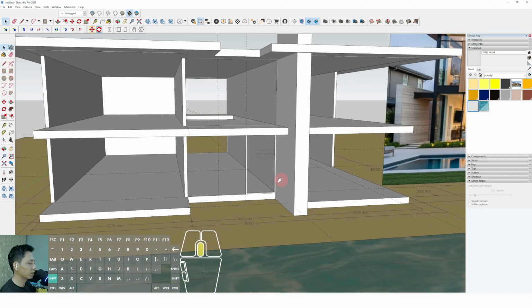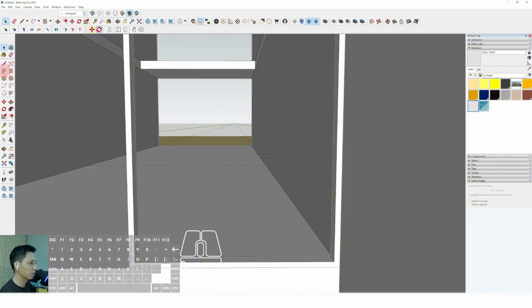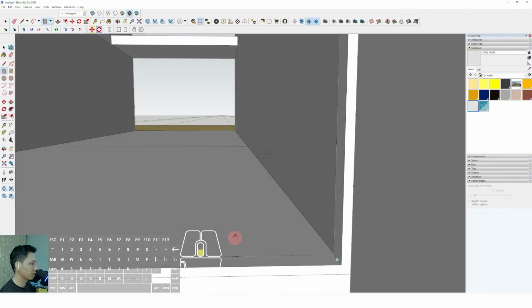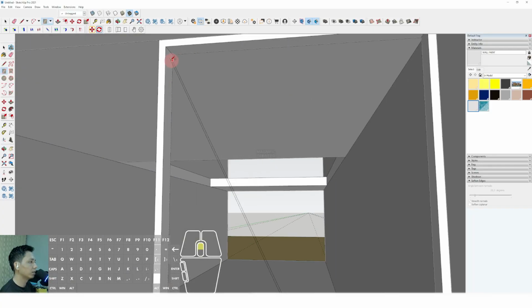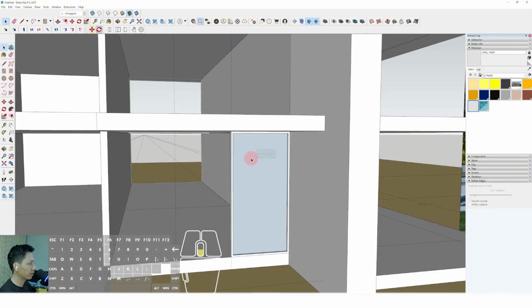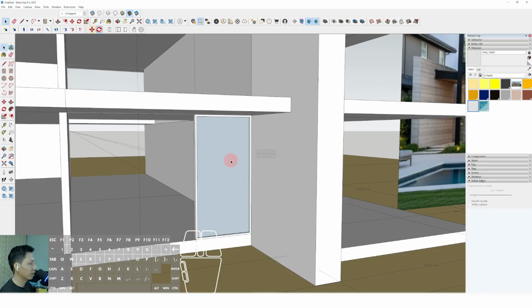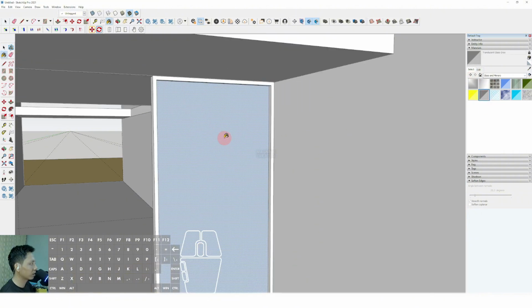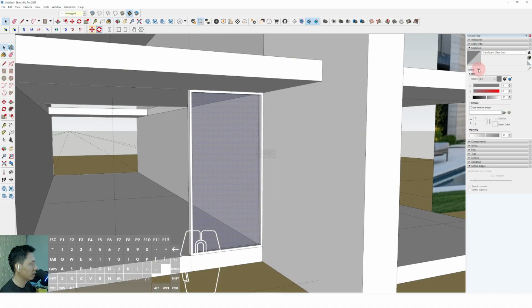Okay, so you can see about the progress. Now we can select the rectangle and click from this midpoint until the another midpoint on the left top position over there. Okay, now we can select the glasses and materials. In here we can select the translucent glass gray and just assign to the surface, and don't forget to edit this item materials. Don't forget to set the opacity and select the color of the glasses. Okay, I mean it was enough.